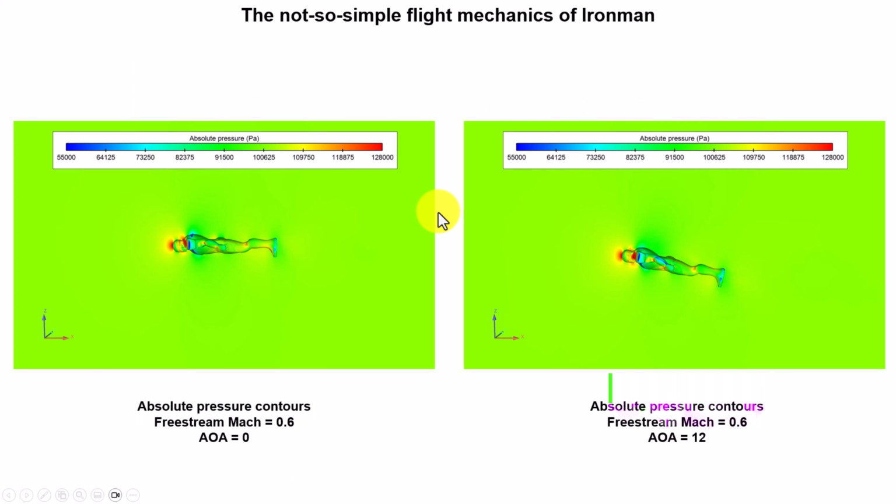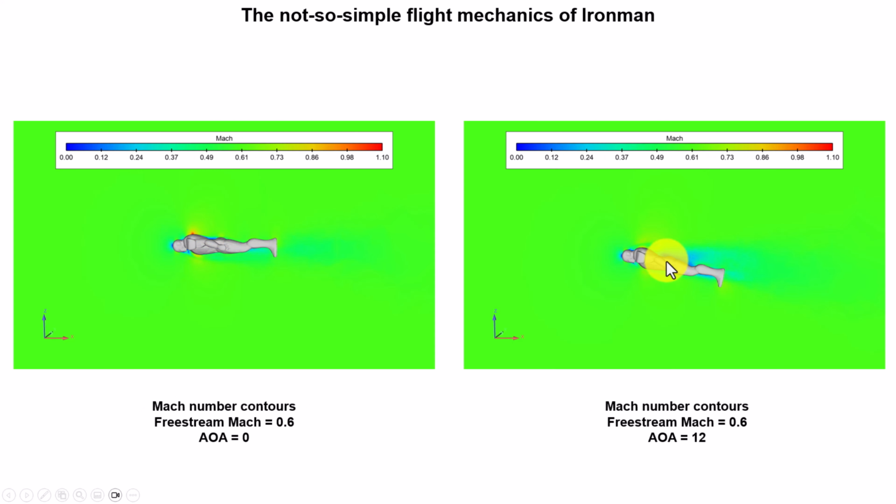And just to compare all those results, those figures were at 0 degrees, and here 12 degrees, to demonstrate how unrealistic it is. Already everything here is science fiction, but how unrealistic is it here now? We don't see in the movie that it is in cruise condition at 12 degrees of incidence. So it shows how unrealistic it gets when you increase that, and if you want to keep it low, to generate the necessary force at Mach 0.3 or 0.6 or whatever, okay? So we also have these results, and here you have more separation, comparing both cases, and that can cause some linear and non-linearities.